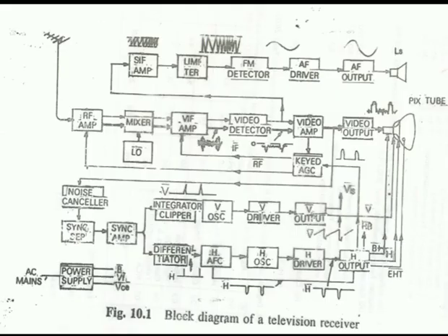We are using the IF preamplifier and SAW filter, and in the video detector we have seen the video IF amplifier, for the purpose of detecting the video signal and separating the audio signal. Then whatever separated audio signal is given to the sound section.